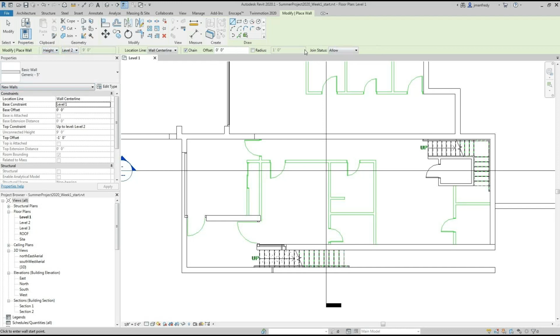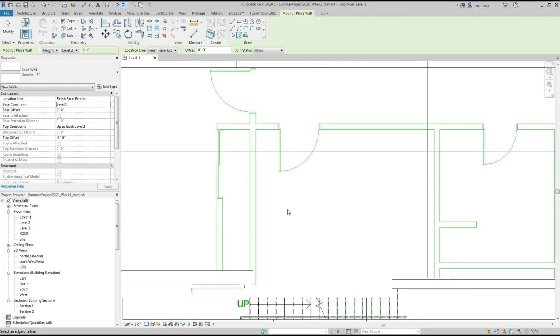That's the beginning, options bar. I want to trace these walls. So I want to touch what would be considered the exterior face of the wall. I'm going to chain them. Okay, fine. If I go around a corner, I want the corners connected, sure. And here, it's not going to have a radius. So when I turn a corner, it's not going to be curved because radius will make a curve between 2 lines around a corner. I don't want that. But here, I want to pick lines that already exist. Pick lines. And I can touch AutoCAD, which makes this a piece of cake. Ignore the doors.